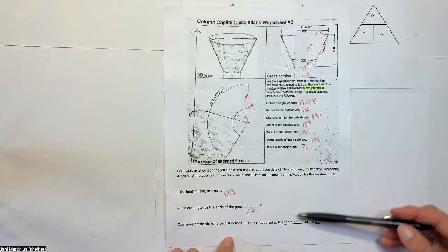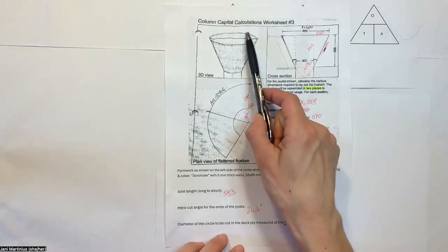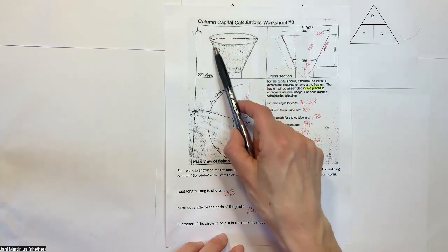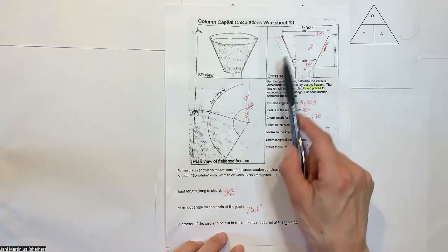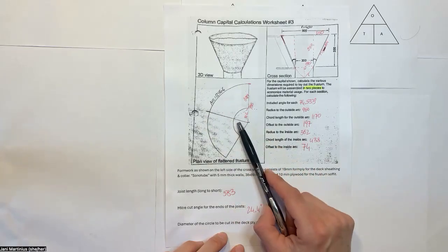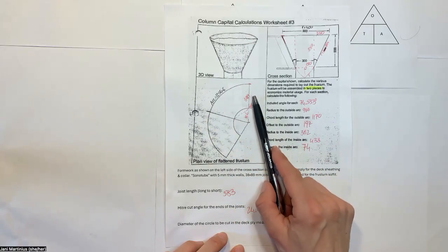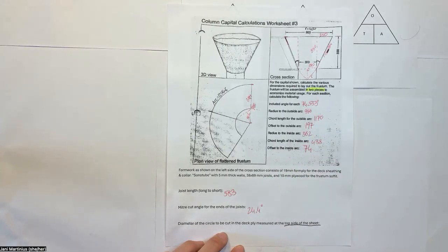Write out, what are you trying to find out at this point right here? And remember that the circumference and radius of the piece in its 3D real-world form is different than the radius once it's on the flat. And to find the arc and the included angle, you need to work with the radius on the flat. And then you just work your way through, figuring out one thing after the other.